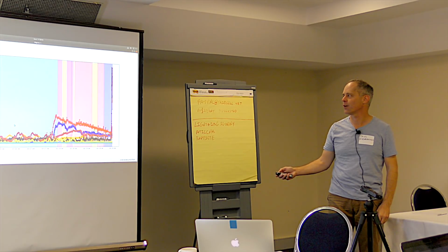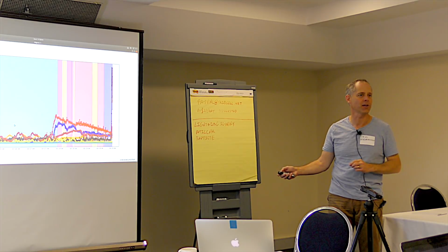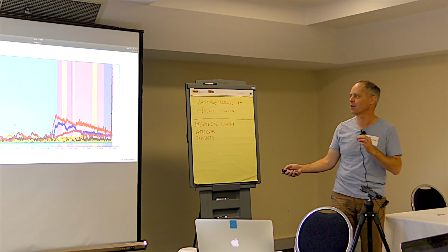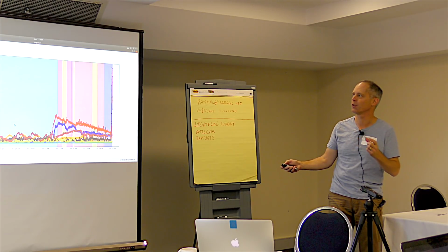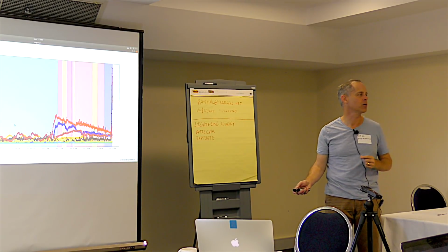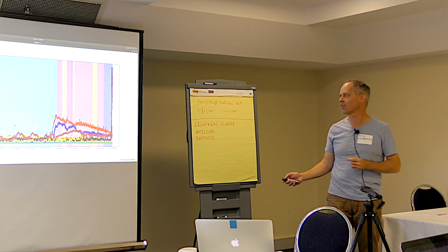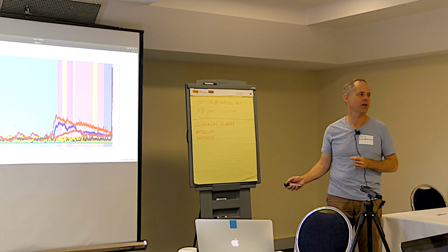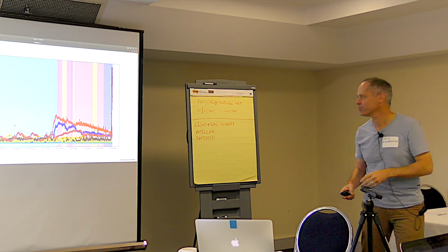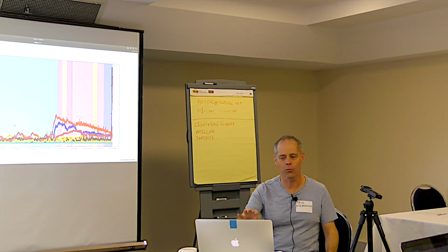You notice that it only affects one EKF, it doesn't affect the second one. So in other words, it's on one IMU and not the other. Now when you see that, it's a fault that appears on the EKF that uses IMU1 and not the EKF that's using the second instance of the IMU, then that's a pretty good clue that there's something going on with the IMU data. Unfortunately, in this case, the user had turned off IMU logging, which was inconvenient.